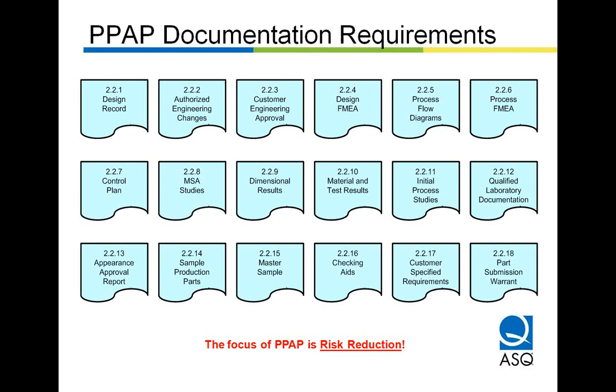Sample production parts can either be correct or incorrect, as in placed on a board so that I can see, in a spot weld application, for example, we might have sample production parts that have an edge weld and have a cold nugget or some other type of specific defect. So those would be your sample production parts. The documentation requirements would be about the same because what we need to know is where they are, what they are, and how they're being maintained.